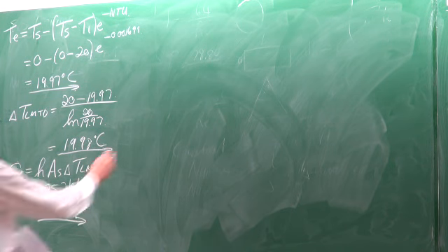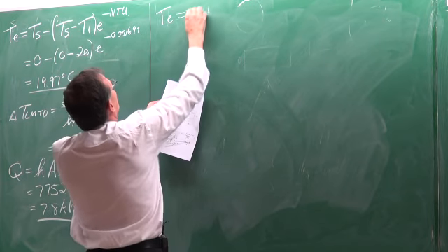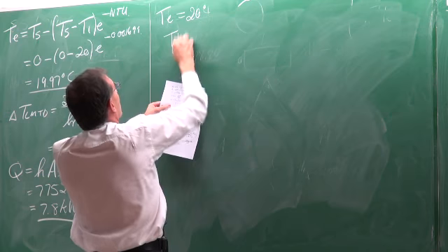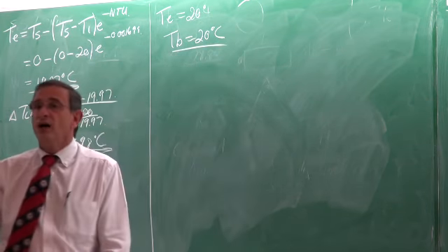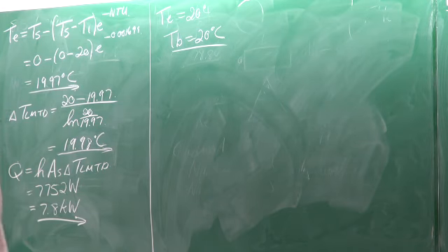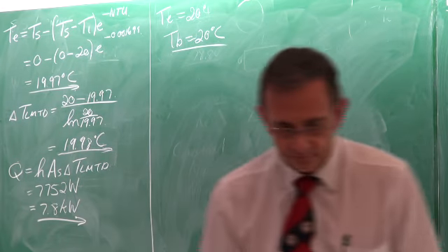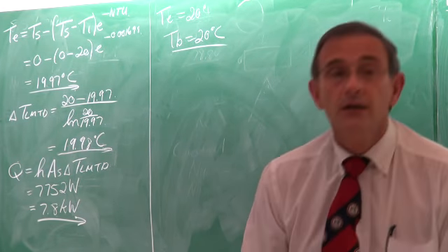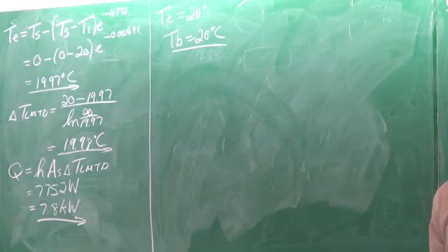So it therefore means that I'm going to say now my TE is almost 20, so my bulk temperature is 20. And at that bulk temperature, I'll have to go and get the properties again. Now look how the properties of oil changed, specifically from 0 to 20. You'll see a significant difference, and you will have to recalculate everything. You all happy with that?